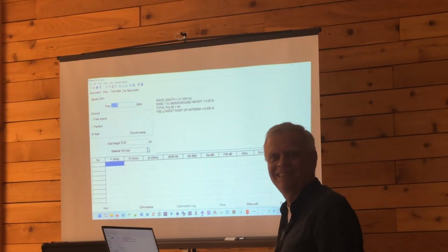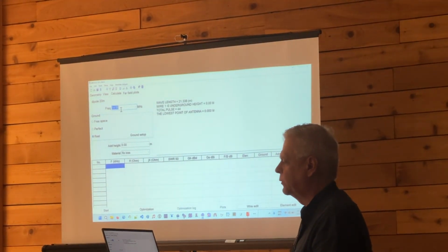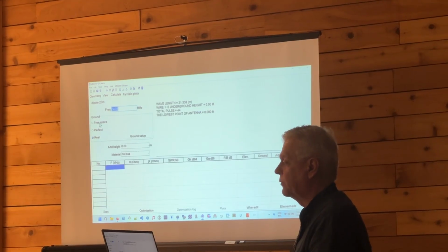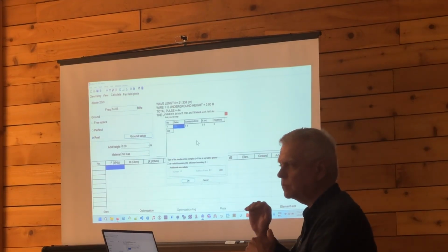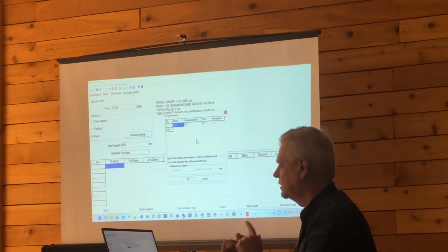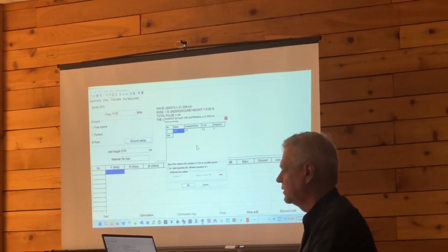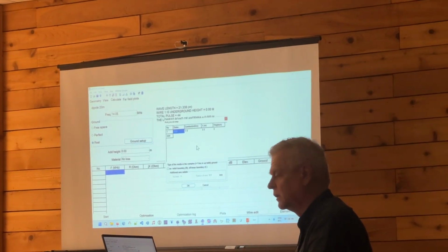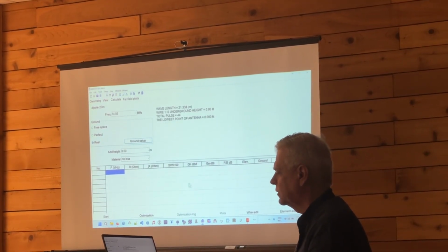Okay. Here's where we put the elevation, the 10 meters, right? So right here, we double check that the frequency is what we wanted. Yes, it is. Staying away from free space and perfect, we go to real ground setup. I guess we can leave radials. I like to check it off. And then, again, just assuming the default, you can find this in the antenna book and in other places on the web, what dielectric constants and conductivities to use for very dry desert-like surfaces, seawater, fresh water, and things like this. So that's where we can get these things. But for now, we just use the default.